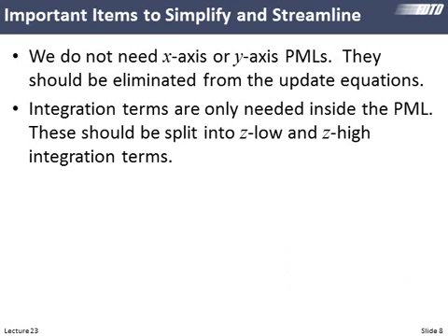So the big thing here is erasing the PMLs at the x and y boundaries. And what we'll see is that our update equations simplify, and there's a lot of integration terms that we will no longer need, and we definitely want to split them so we have PML terms just associated with the top and the bottom. Before we were integrating these PML terms everywhere, we pointed out this is inefficient, but not such a big deal for 2 dimensions. But when we move into 3 dimensions, that is a big deal. So we need separate integration terms now for each PML region.